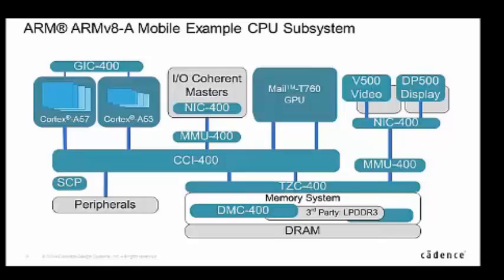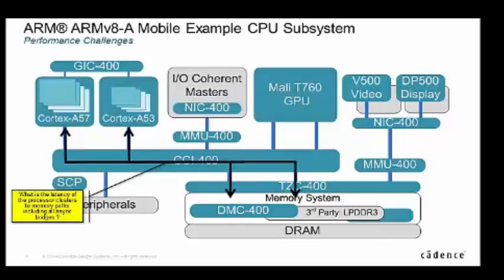You want to know, for instance, and CCI is a case in point, did a transaction have a cache hit, as in a snoop hit into the L2, or a snoop miss? What was the different latency based on snoop hits and misses? And ultimately, what else was going on in this environment to try and debug it?